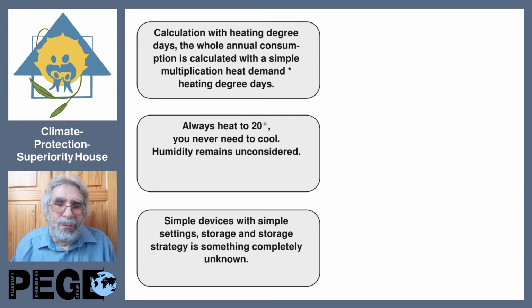In this area, it's possible to leave humidity unconsidered, but when you want to build the house somewhere near a hot jungle, air temperature 35 degrees, 90% humidity, and when you cool down this air, the humidity goes above 100%. How is this possible, above 100%? What's more than 100% is water running down the walls.